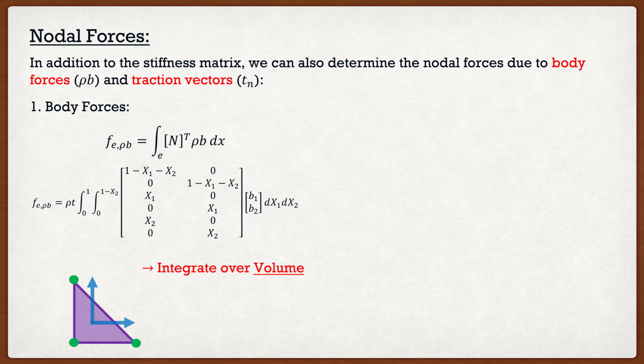It's not a function of just all the forces throughout the element. So what we need to do is take these body forces that are due to things like gravity, and convert them into equivalent nodal loads. So we're taking that gravity load that is present throughout the entire element, and we are simplifying, creating an equivalent load representing that gravity located at our nodes, so we can account for them when we're solving our system.